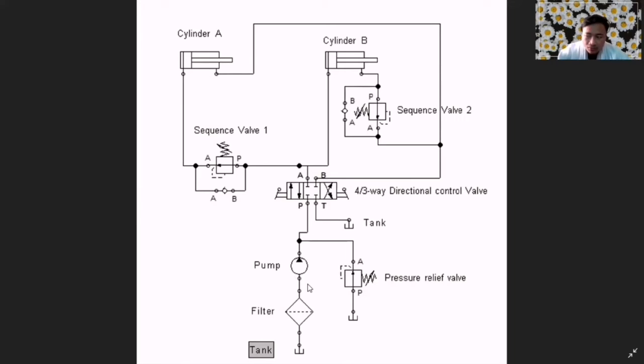The double-acting cylinder is also a component in this circuit, which alternates cycles of pressure fluid to both sides of the piston and creates extend and retract force to move the piston's rod, permitting more control over the movement. And last but not least, the component we use is the sequence valve, which controls the sequential operation of multiple actuators. The sequence valve has an actuator that diverts the medium to another part of the system to execute the next command in the program sequence.